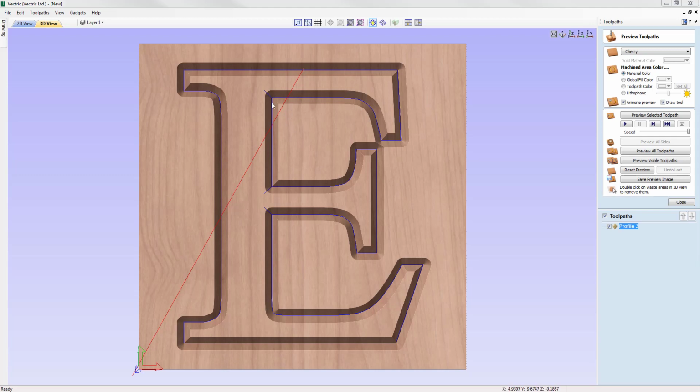And so we can see just by looking at the toolpath, so you can see these lines here, the toolpath now taken the tool edge up into the internal corners. And if we go ahead and preview that, we can see now that the corners are much better defined, where we have nice internal sharp corners. And the software's achieved this by retracting the V bit up slowly into the corner to create this sharp internal corner and sharp internal beveled edge. So all we need to do now is run the cutout pass using another profile toolpath.